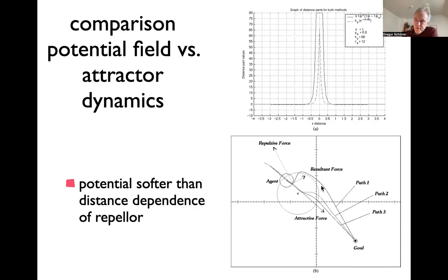While in the potential field approach, you just know where you are, and there's always this repulsive force from where you are. Even if you're already heading away from the obstacle, you will keep being pushed in that direction. Essentially, in terms of the gradient, there is a repulsive force that is being felt as long as you're within the range of the obstacle. So you want to have a large range so that you don't make these last minute maneuvers. But when you have a large range, that means you're still influenced, even though you're heading away from the obstacle or heading sideways. It's less sideways. So that's also a drawback.